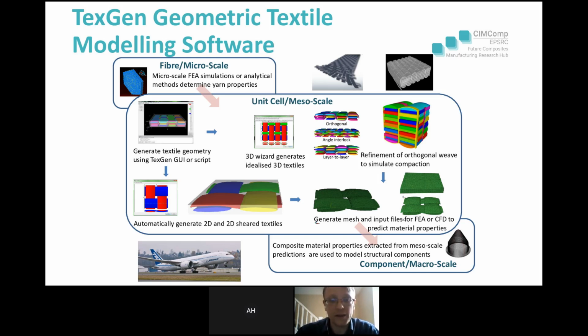What is important here is that it's possible to program TexGen to create these models in an automatic fashion. So we can parameterize our model by several parameters and generate it in batch mode, just driving it from an external program. And for any optimization framework, the ability to generate models quickly and without any user interaction is very important.